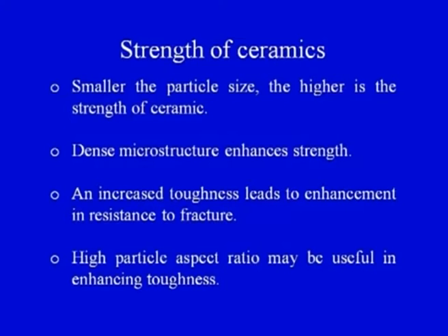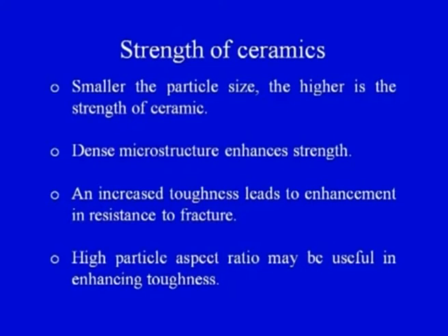Now, coming on to the strength of ceramics. Strength is a very common word which has been highlighted here. So, strength can be tensile strength, compressive strength, shear strength. The strength of ceramics basically is dependent on the particle size: the smaller the particle size, the higher is the strength of the ceramic. Different particles make up the ceramic, because we will see powder processing technique for processing of ceramics. There we will see how we will blend the powders together to make a ceramic product.